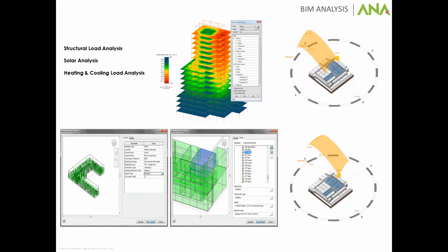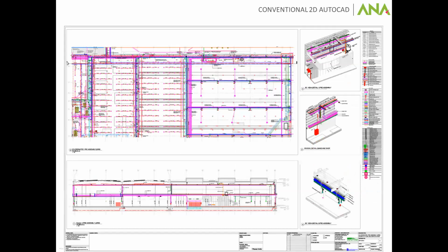I apologize for this. So then, we suddenly had this free, relatively cooler air available to us, which was 3 to 4 degrees Celsius lower than the ambient. We used it as the fresh air input for the air conditioning system. So now the air conditioning system, instead of having to bring down air from say 47, 48 and bring it down to 24 or 26 or 27, depending upon where we were trying to maintain the temperature, was now bringing it down from 42.